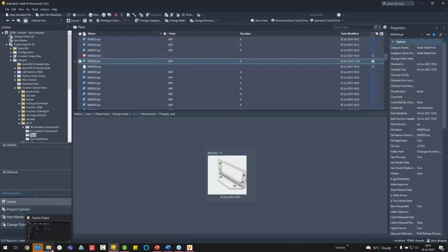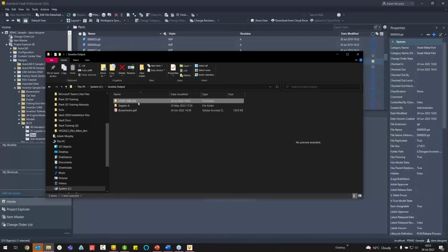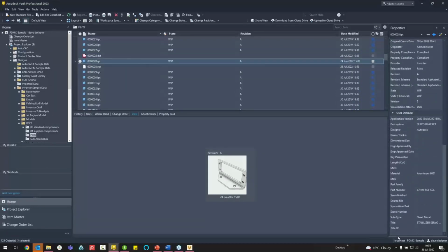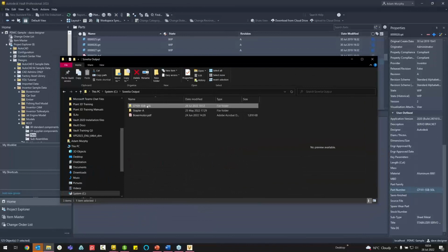And just to prove the network side, you'll see the very same file appeared in a folder which is named after the part number. So if I take this file name 0028, scroll down, I'll find the part number for this is this value here, and I'll find in my network folder location that a folder has been created. One minute ago, this folder was created and the DXF and the step file were loaded into this particular folder. So that's the key.